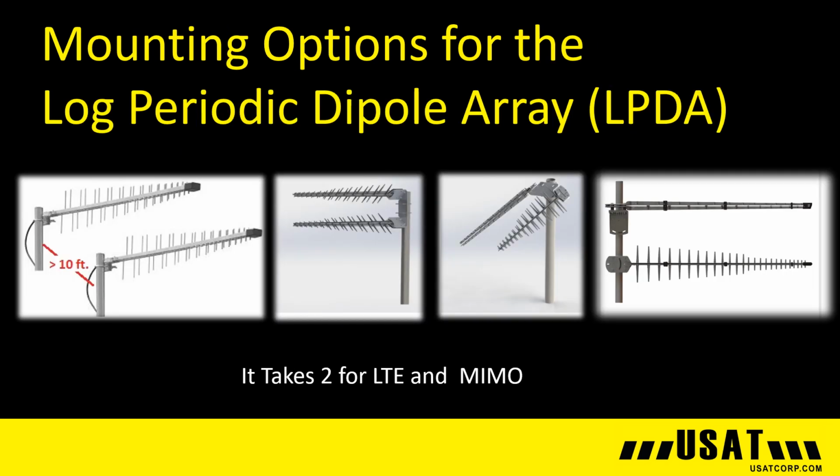A little closer look at the mounting options for the LPDA. As mentioned, the optimal solution is to mount them 10 or more feet apart on separate poles. However, many applications are space constrained, so we have a bracket that will cross-polarize the antennas. Here, the two orientations you can mount the bracket on a pole with.